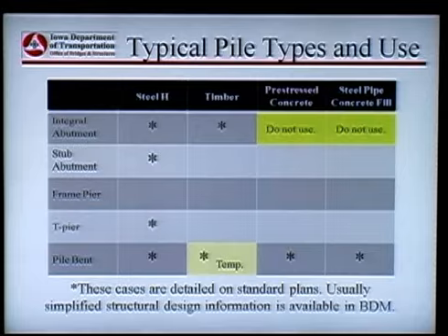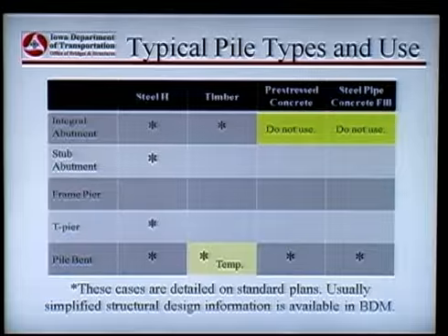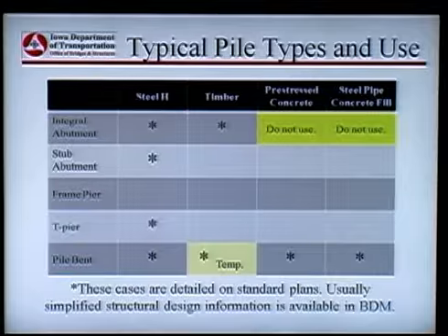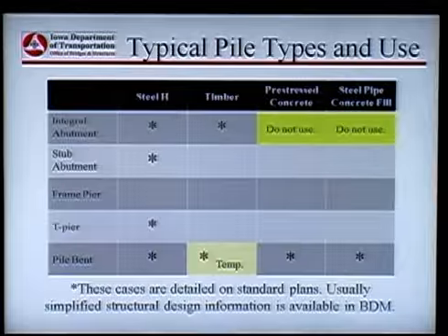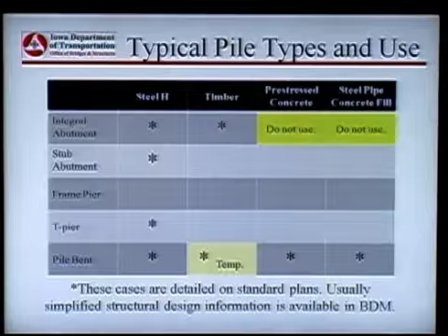We do not use or recommend either pre-stressed piles or the pipe piles for integral abutments. There was one county project where it was tried as part of an Iowa State research project to use pre-stressed concrete piles in an integral abutment. And they found some annoying cracking down below the abutment when they dug in and checked it. So that's kind of been tried, and it doesn't look good. So we don't recommend it, and we don't recommend the steel pipe either.